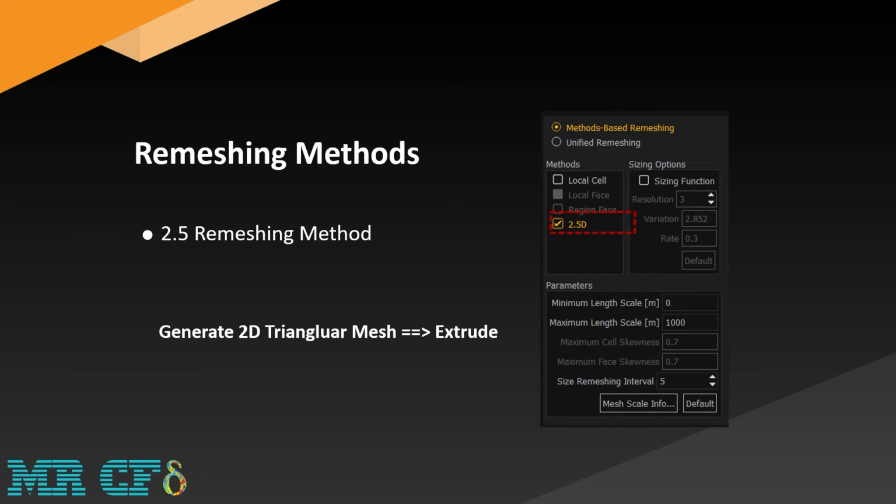In fact, this method is the 2-dimensional triangular mesh that is expanded or extruded in the direction of the normal vector of the specific dynamic area that we want in modeling. In other words, the triangular surface mesh is remeshed and smoothed on one side of the mesh, and then the changes are extruded to the opposite side.